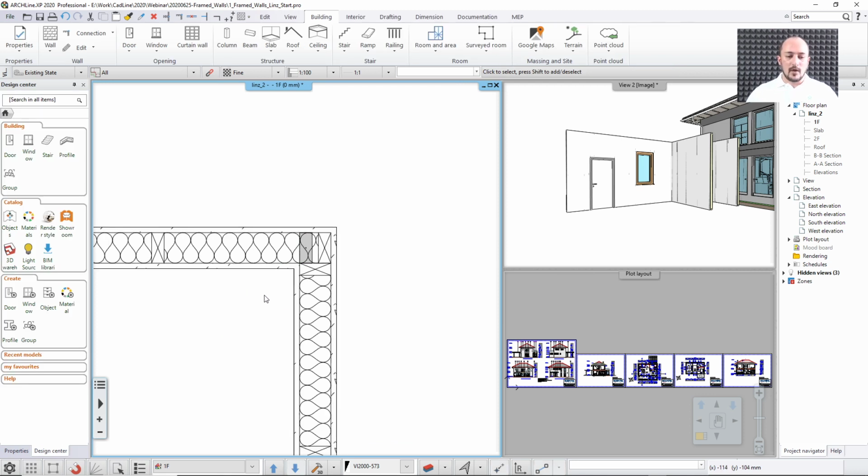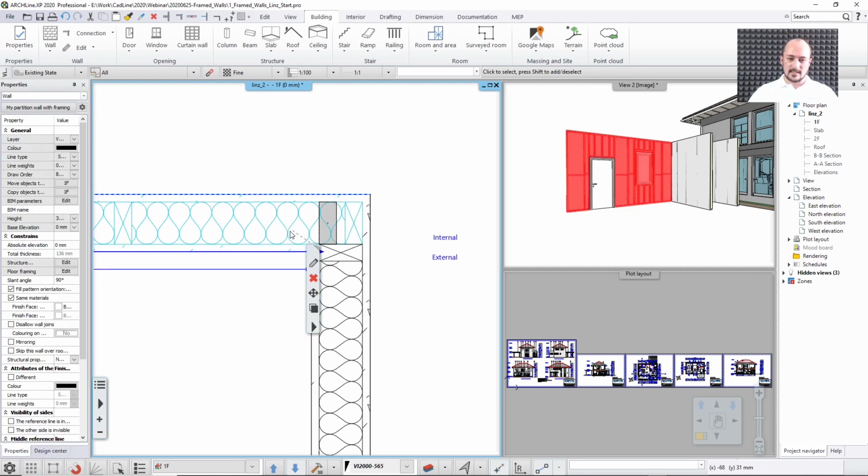So now there is one thing that regarding the 3D and the 2D together is not correct here, and that is actually this column is now not nested into this wall. As you can see, when I select this wall, this column is not selected, and also unfortunately the thermal insulation and the stud are kind of intersecting each other. The stud should not have this thermal insulation here.